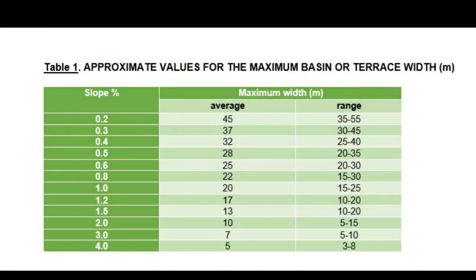Here is a table of approximate values for the maximum basin or terrace width in meters. The maximum width depends on the slope percentage.